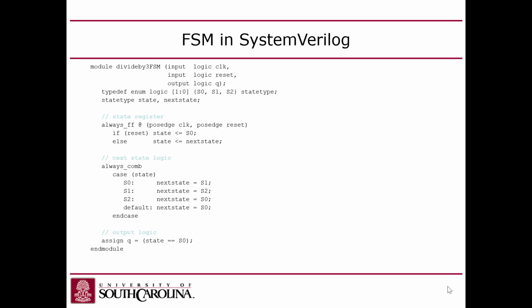The number of bits is going to have to be, I don't know why it doesn't do that automatically, because the number of bits would have to be the log of the number of states. So there's 3 states, so the log base 2 of that rounded up would be 2 bits, right? So they have to declare it as 2 bits. Yes? Maybe it's so that you could pre-allocate if you're prototyping and you don't have your full state space figured out yet. But you're going to need states later. Yeah, that could be. It's a lot easier to parse from a compiler standpoint. Could be that, yeah, or it gives you room for expanding the number of states.